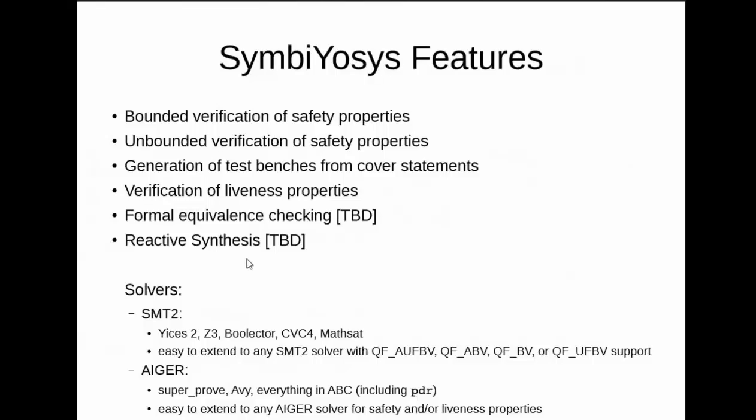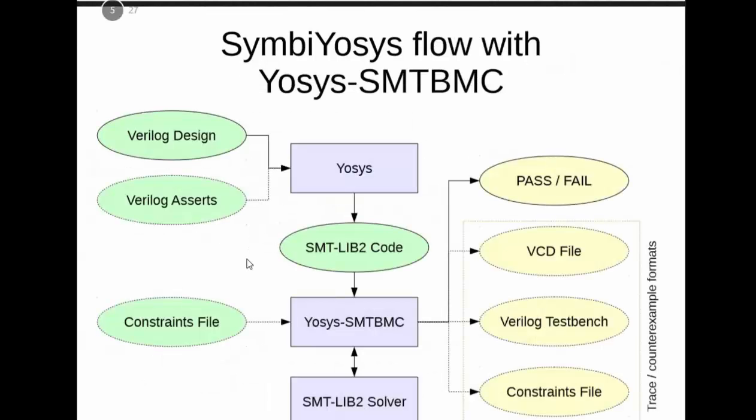So for those of you who don't know, reactive synthesis is essentially synthesizing a circuit from the safety properties you provided. And there are a couple of applications for that, but I personally like this to evaluate my safety properties, because if I have a traditional test bench and then I synthesize a circuit from my safety properties and it doesn't pass my test benches, then this is a good indicator that my safety properties are not really sufficient to describe what my design should do.